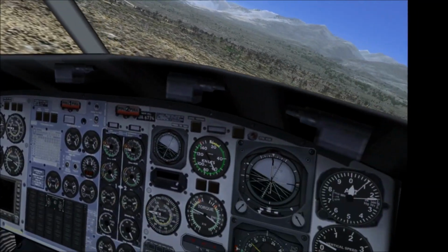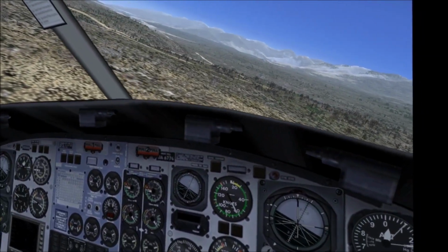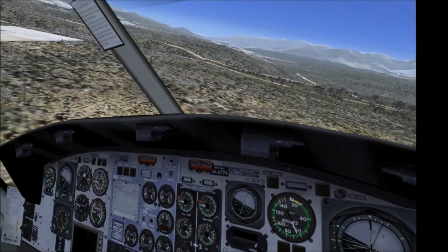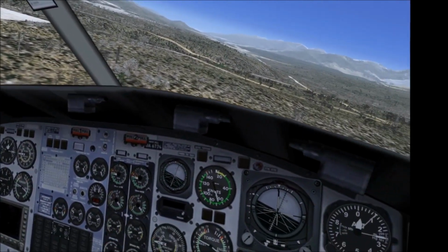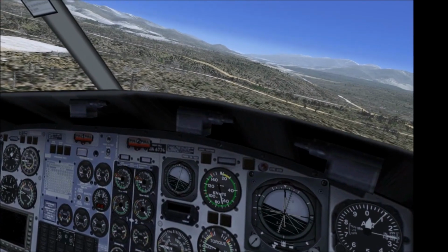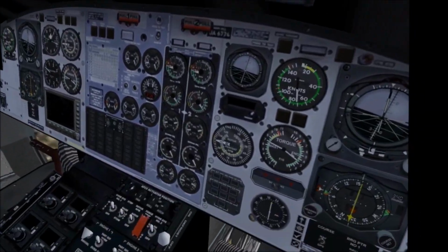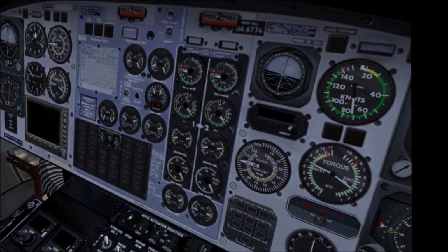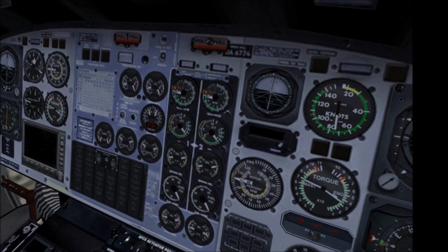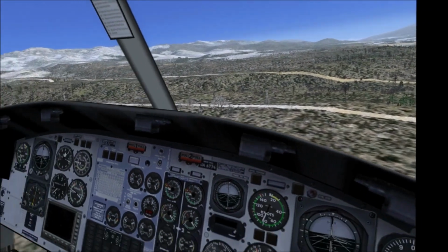And that's really what's going to be limiting our power. That's really what limits our power all the time when we're dual engine in this model. But we're going to pay more attention to it today, because that's the limit we're going to exceed first. Looking at our N1 numbers, we're pretty high on.